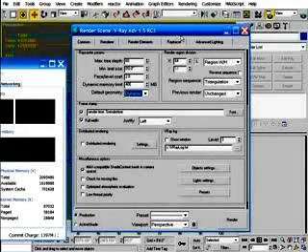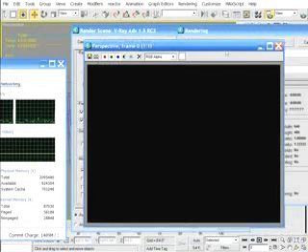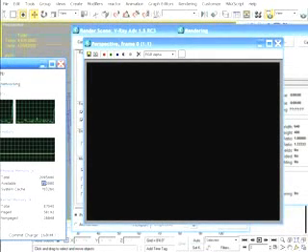The downside to using dynamic geometry is that it can cause a significant increase in render times because of all the time that VRay spends transferring information from hard drive to RAM and vice versa. But nonetheless, it's often the only way you're going to be able to render very large scenes without running out of RAM, and when it's needed, it becomes an invaluable feature. So if I render the scene again in dynamic mode, it will have no problem completing the rendering, and in fact, the amount of available RAM changes very little during the rendering process.